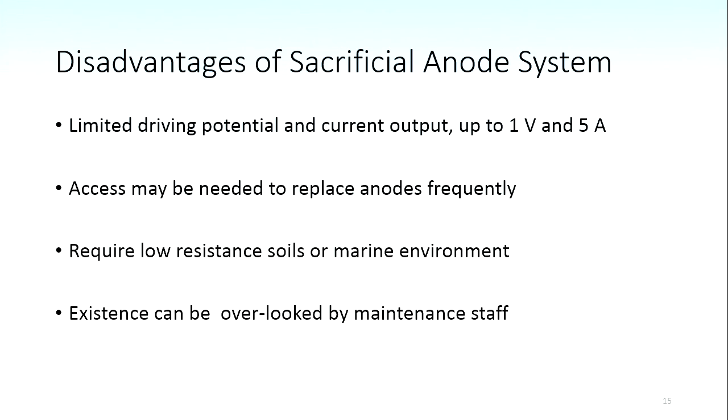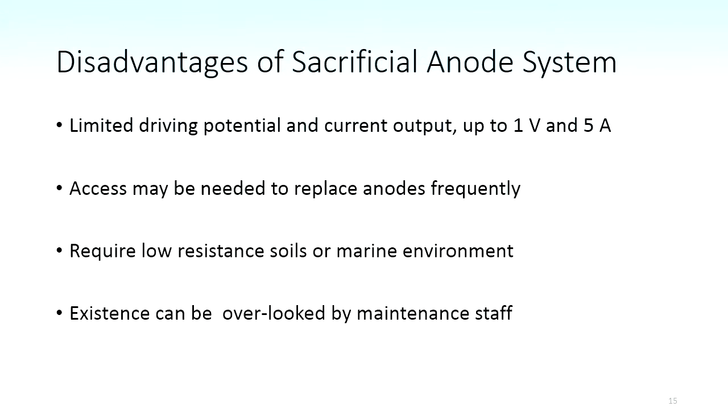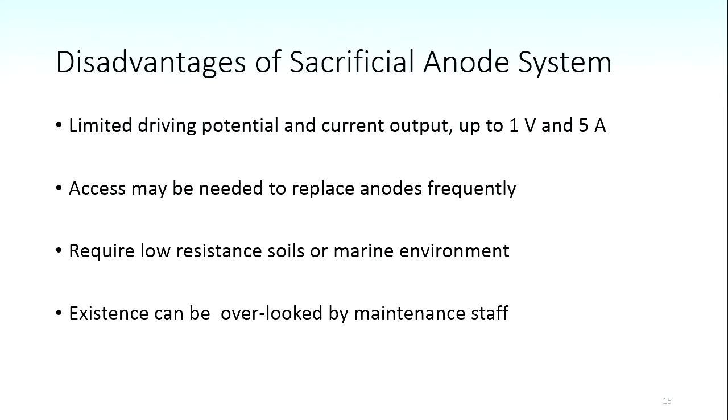then this sort of system doesn't work very well if the resistance of the environment is high. It works fine in marine environments, when there's a high conductivity saline solution. It works fine in reasonably conducting solids. You may need to be in to replace the anodes, depending on what ratio of anode to cathode size you've selected in your initial installation.